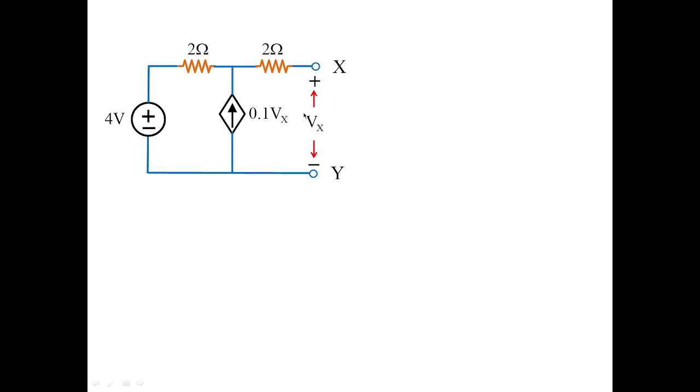Now for the given circuit, we have found that Vx is equal to 5 volts. The so-called mistake is being rectified over here. So VOC or Vthevenin or Vx is equal to 5 volts, and I short circuit is 1 ampere. Therefore, applying the Thevenin's resistance formula, we obtain the value of Thevenin's resistance equal to 5 ohms.